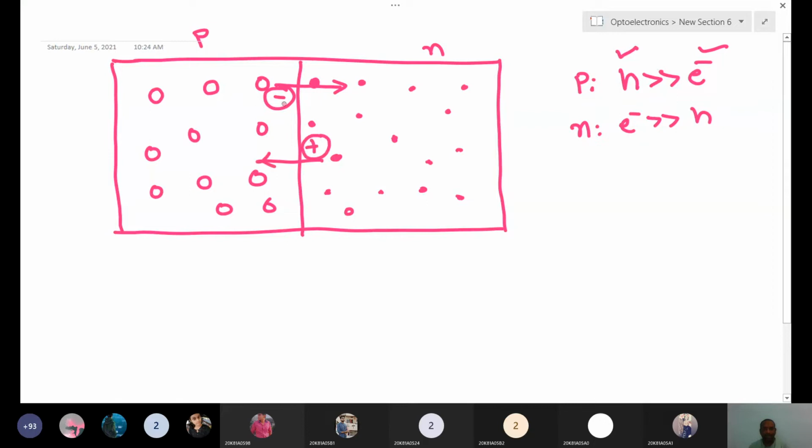This negative and positive charge density is immobile. Similarly, on the left side towards the P side, negative charge is induced, and on the right side, positive charge is induced. We have discussed this already. This is a depletion region, or space charge region, you can say. Once this positive and negative charge is developed, there is an internal electric field,